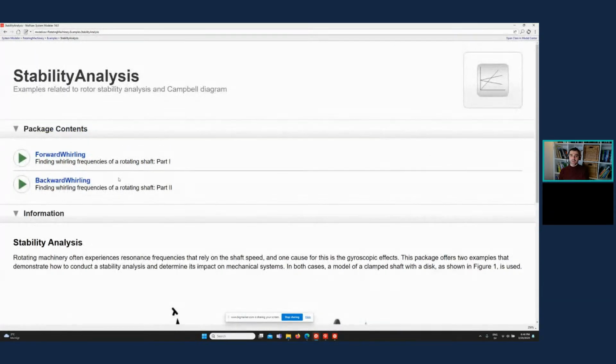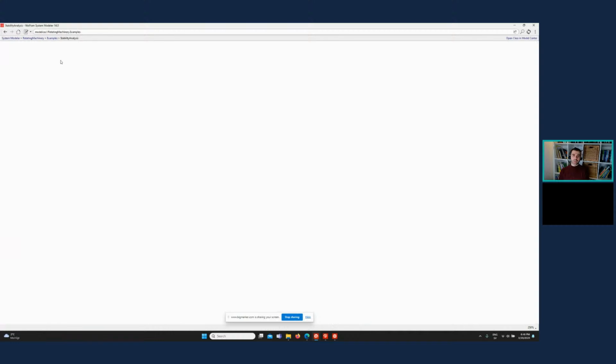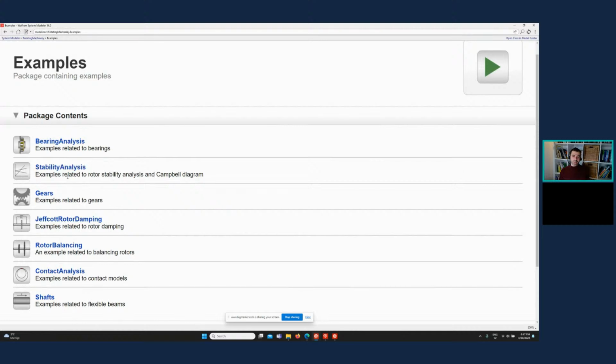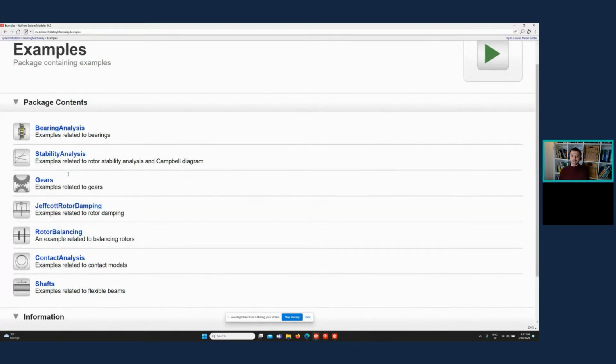These are pretty useful analyses. Assuming you are running a machinery and then you change your mind and decide to run the machinery at a different speed, before doing that you need to be sure about whether you are crossing the whirling frequency. I guess simulating this is cheaper than testing in real life. You can check whether the machinery survives at that new rotational speed.